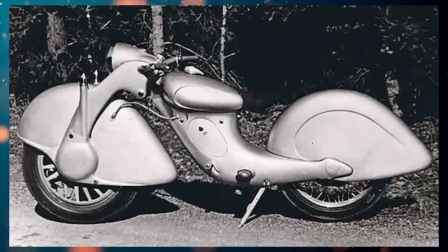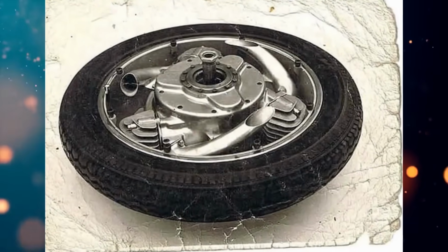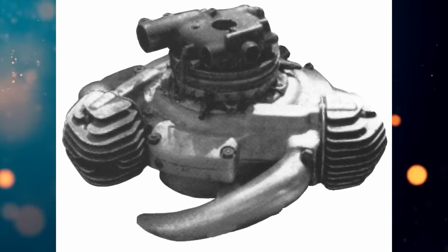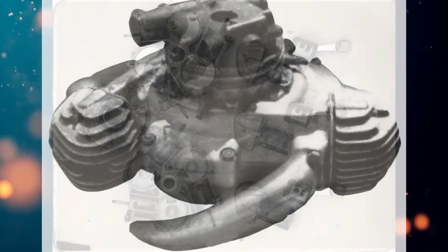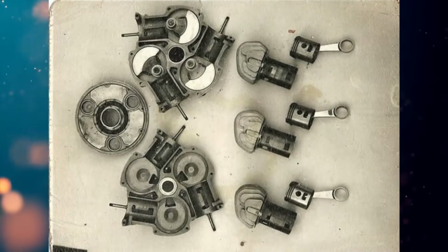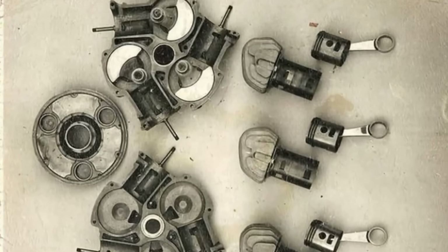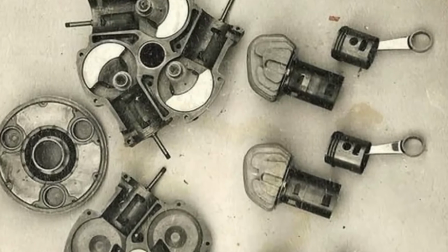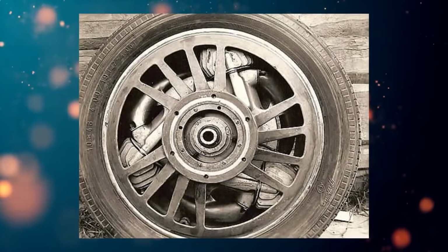Killinger and Freund featured a 3-cylinder 2-stroke engine with a 600 cubic centimeter displacement. Like the Magola, this prototype used a planetary transmission, but engineers took it even further. Take a look at this photograph. This radial engine doesn't have a common crankshaft. Each cylinder has its own, which drives the small gears of the planetary system. There were 2 planetary gears with different ratios.